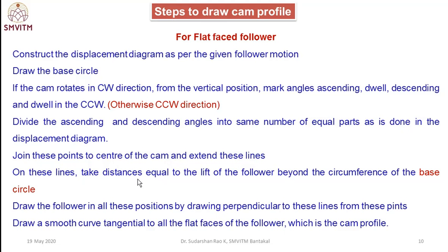Then on these lines take a distance equal to the lift of the follower beyond the circumference of the base circle. Then draw the follower in all these positions by drawing perpendiculars to these lines from these points. Then draw a smooth curve tangential to all the flat faces of the follower. So this is the required cam profile. So steps to construct the cam